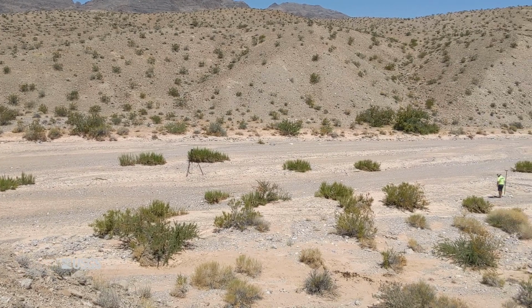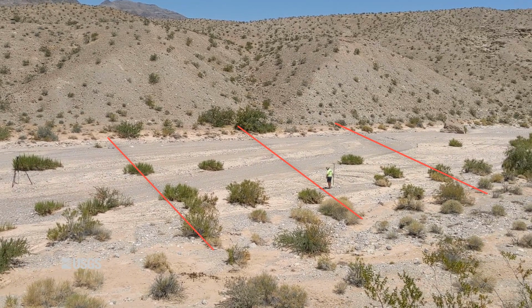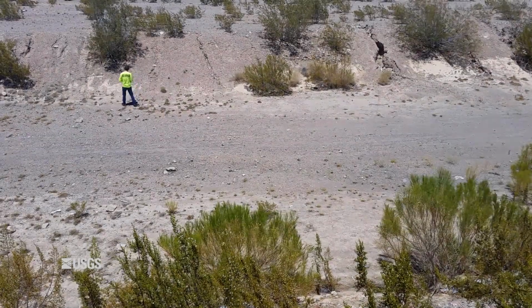As we learned in the last video, the field data required for a slope area measurement involves surveying the channel cross-section geometry, high watermark profiles along each bank, and then estimating roughness coefficients. First things first, though, we have to flag our high watermarks.